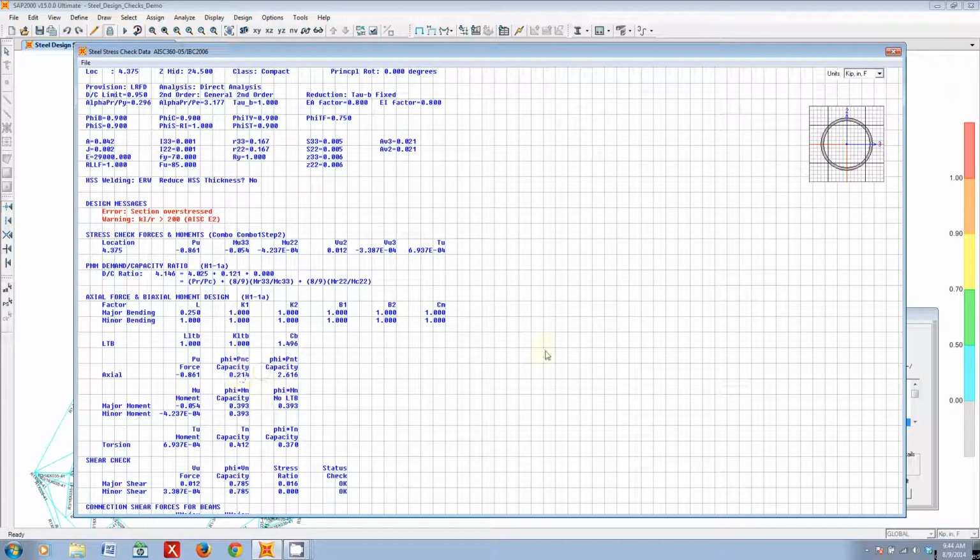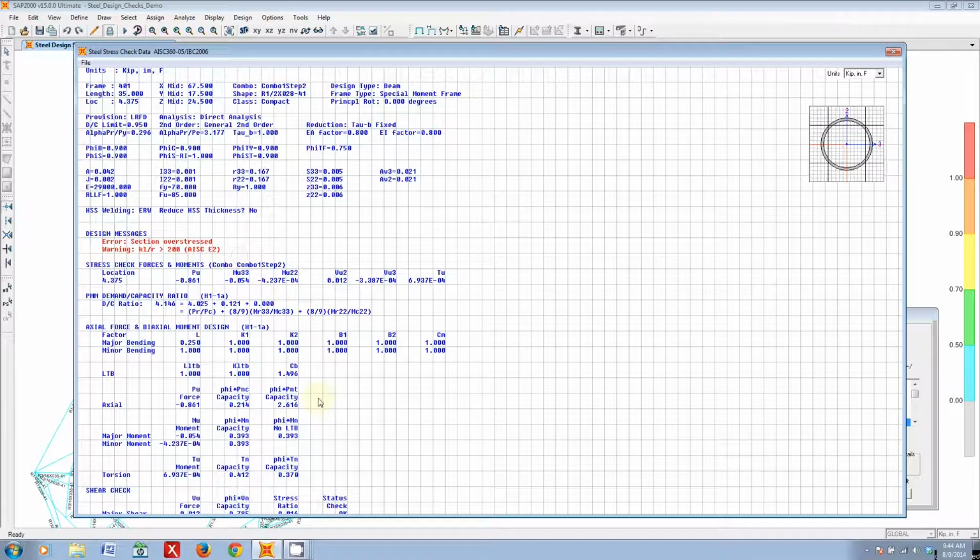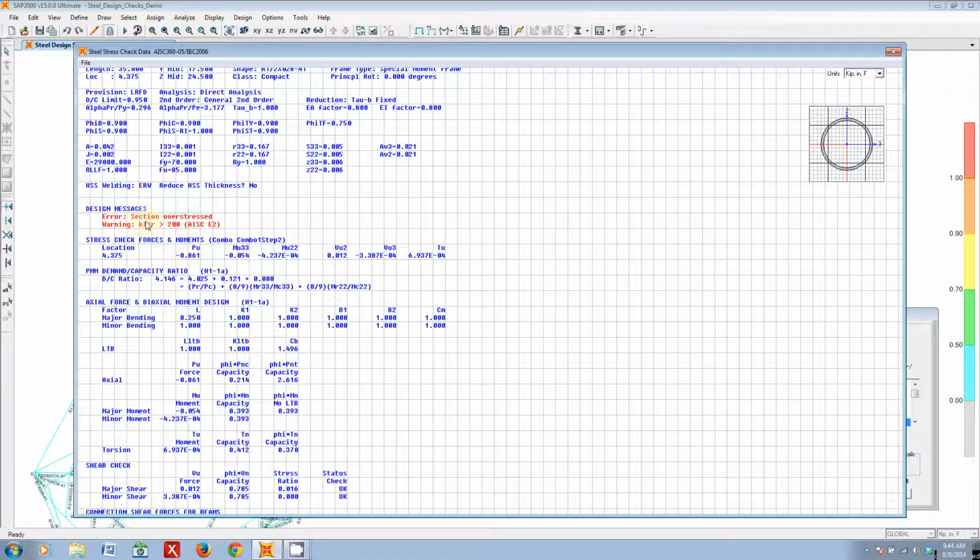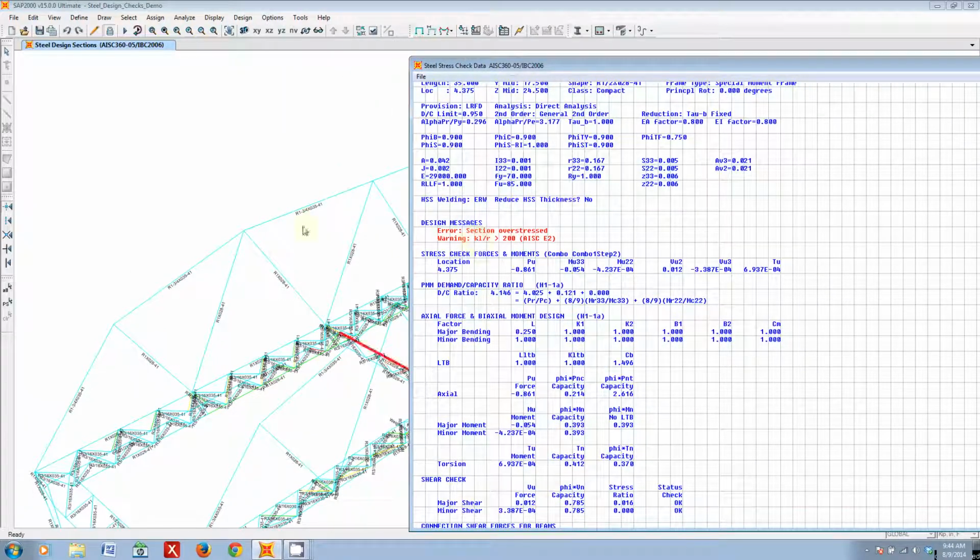Well, we could try to increase the cross-sectional area of the member, but that's not going to do a whole lot. Really, the meat of how you can improve your axial capacity in compression is by improving your KL over R-min ratio. So K, of course, is the fixity coefficient. Maybe you had a top chord member that was pin conditions at the ends. We could change those pin connections to tube-in-tube connections, and then it would have a greater fixity, and thus the K would change, and we would get a higher capacity.